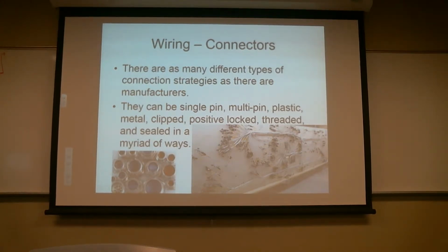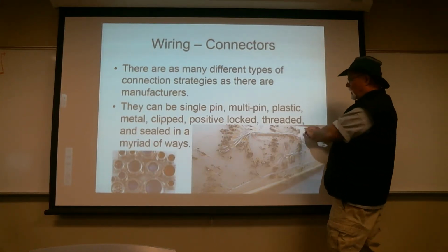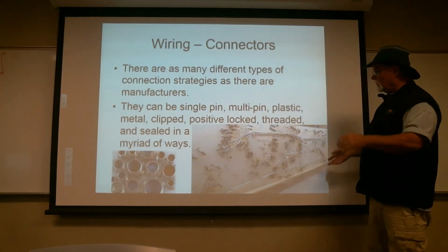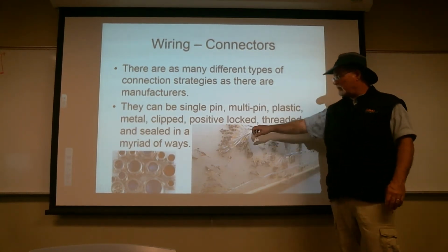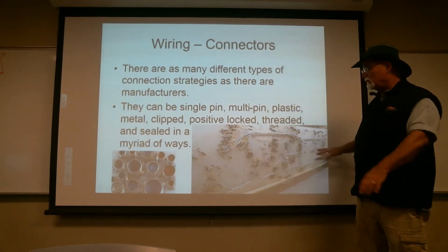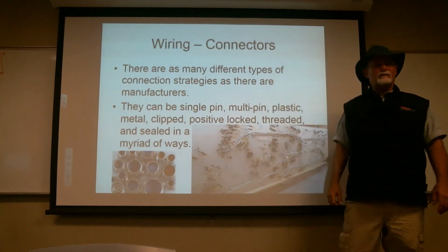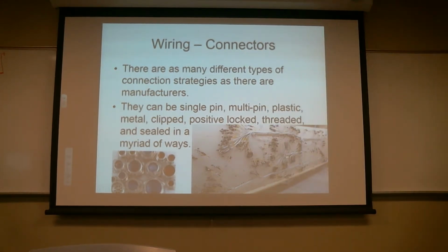Pull that off, set it on a rack, get the next wire, set it on a rack, so you get a whole rack for all these different wires. While that's happening, somebody's job is then to pick up each wire and lay it out, put all the heat shrink in, do all the stuff, sort of clamp it in place, and then once all the wires are laid in place, somebody then comes back and fastidiously goes through and does all the connectors. It makes all the connectors at the appropriate length.